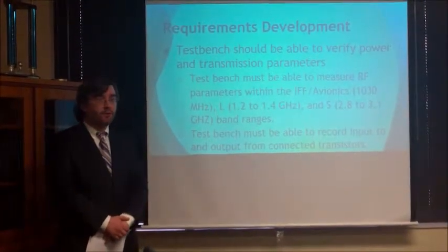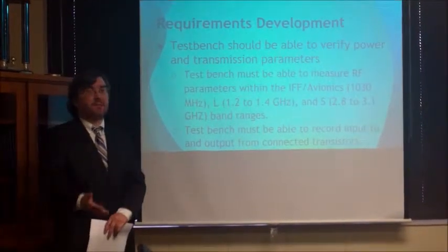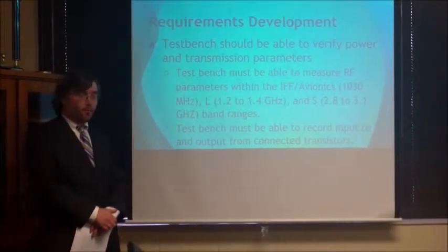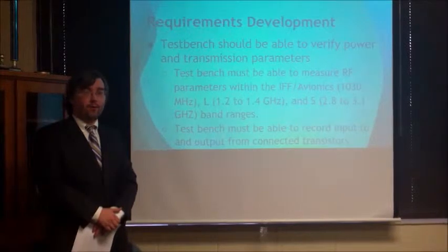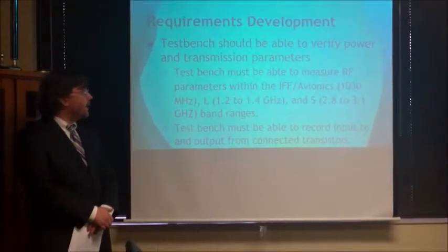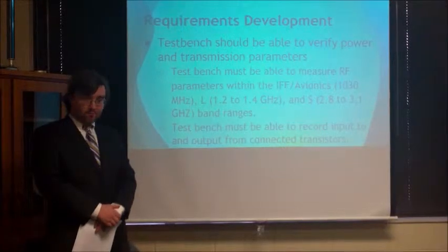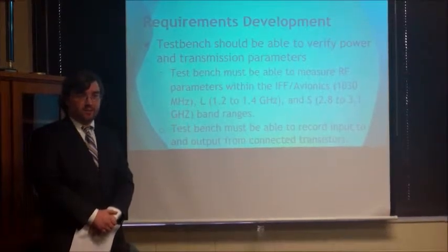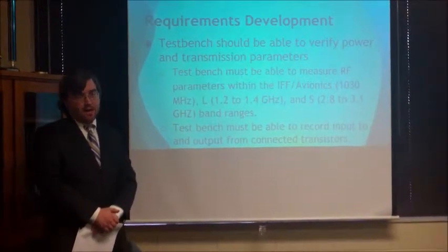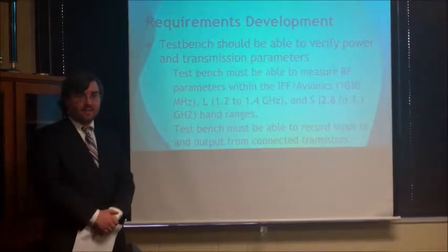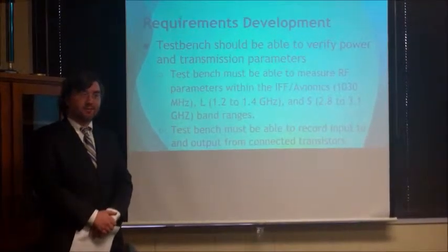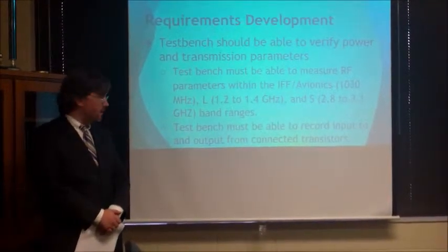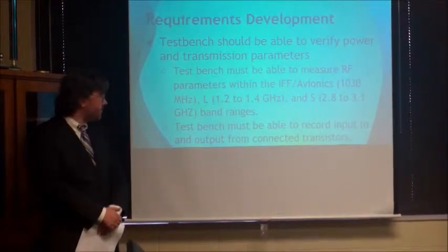Now we're going to move on to the actual requirements of the board. At the most basic and highest level, the board is meant to test and verify high-power RF transistors. It must be able to do this on a range of bandwidths and on at least two types of RF transistors, gallium nitride and laterally diffuse MOS technologies. This is challenging, as connecting various types, despite connections being standardized, has various challenges in how you tune the board.